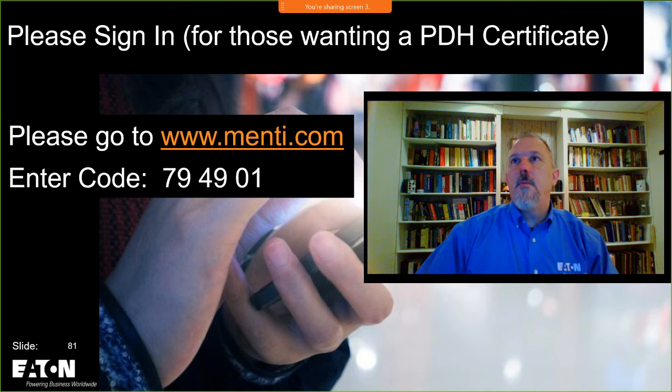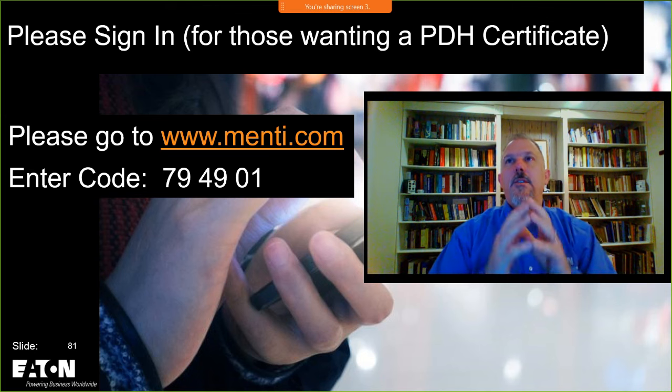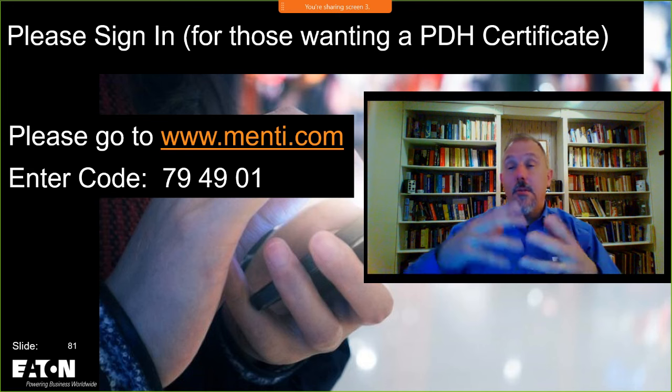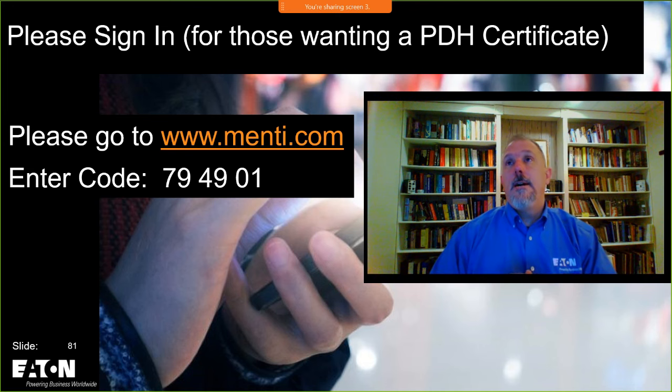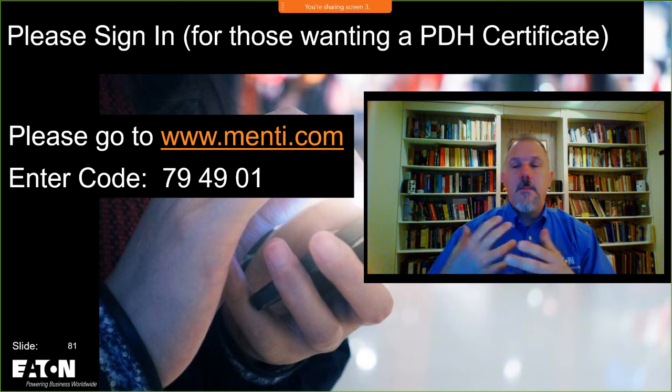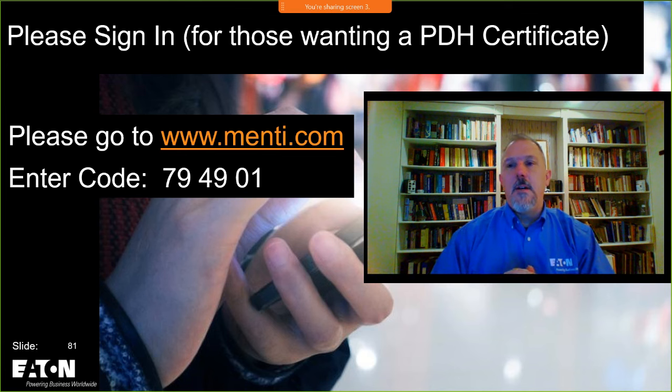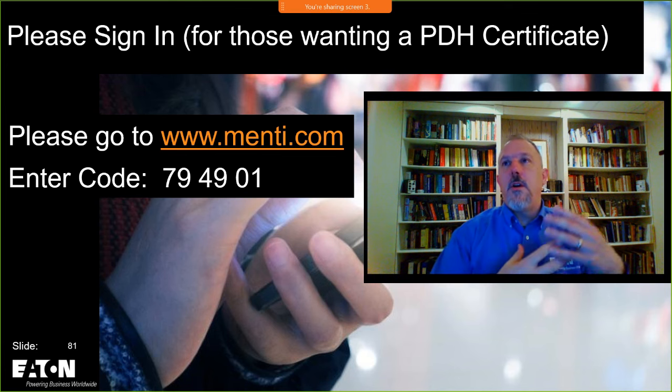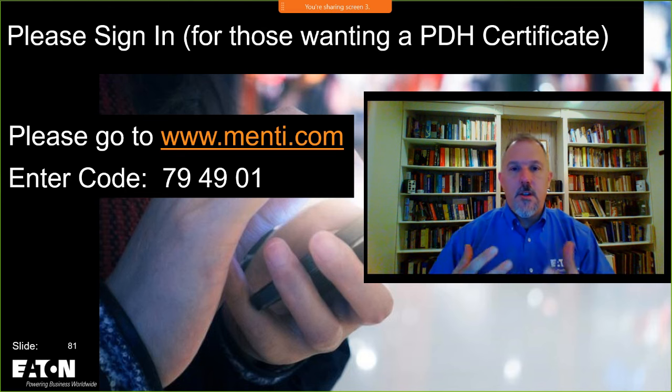You asked me to clarify a bit more about 120-volt smoke detectors where AFCI is required. So smoke alarms, you're required to have smoke alarms in a residential home. But some of the discussion in the past has been, well, I don't want to put my smoke alarms on an AFCI protected circuit because if it trips, then I don't have my smoke alarm.